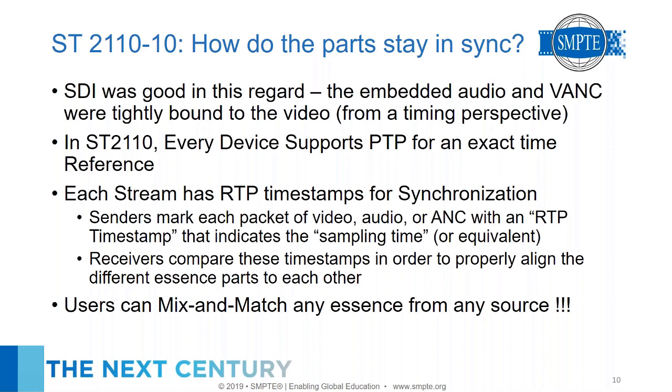The key element in 2110 is Precision Time Protocol, or PTP. Every device that does 2110 supports PTP, and so every device has a very accurate time reference and knows what time it is. So when you generate a video stream or an audio stream or an ANC stream, you put an RTP timestamp on every packet you generate.